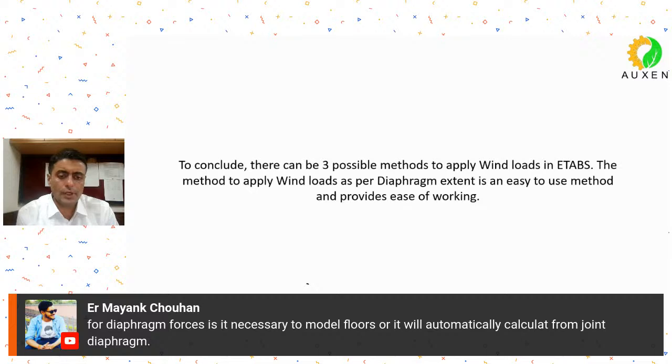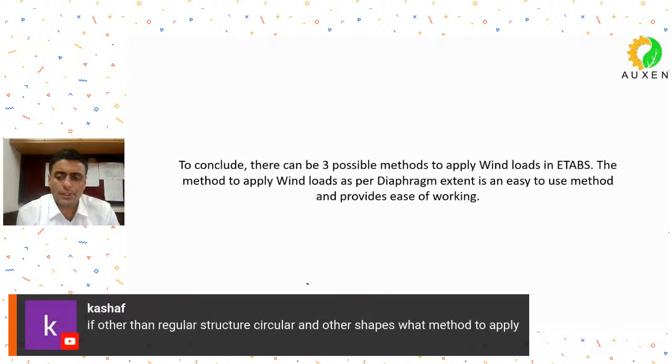I mean, yeah, you have to model floors, right? Oh, okay, he is asking, do you need to model the shell elements or will it automatically calculate from joints? Yes, this is one thing that I did not check, but I think it should do it if you don't model the shells and if you only work using joint diaphragm assignment. I think it should work.